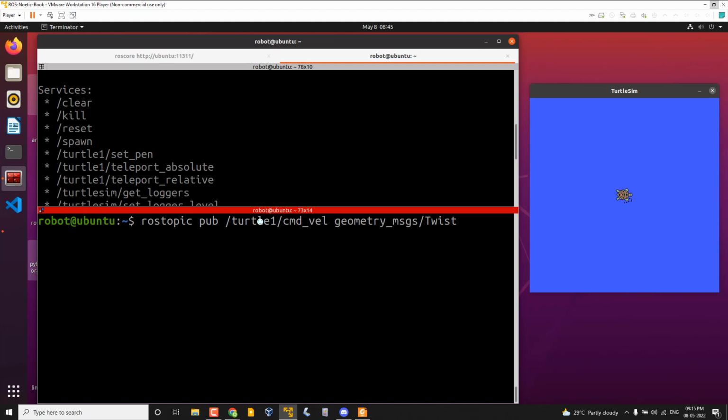Okay, basically this command velocity is the ROS message Twist. It is from geometry messages. Yesterday I showed you different standard ROS message packages. One is geometry messages. Inside that there is a very popular message called Twist. And this is what we are using for any mobile robot.